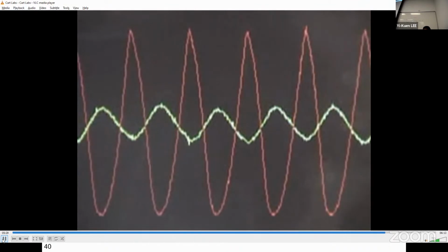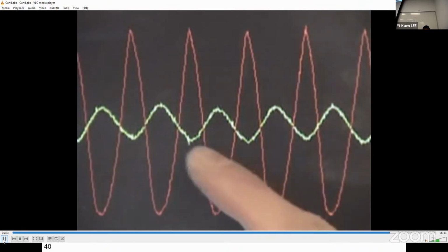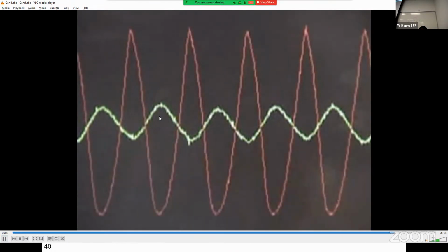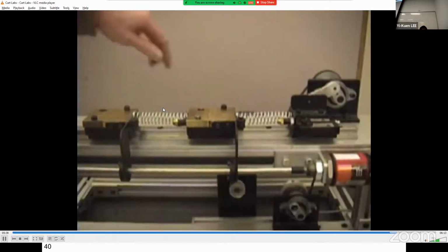So there we're running a little more than twice the natural frequency. And you can see at higher frequencies, there's very little output amplitude. And the output does lag the input by almost exactly 180 degrees. Vibration output would be much smaller.